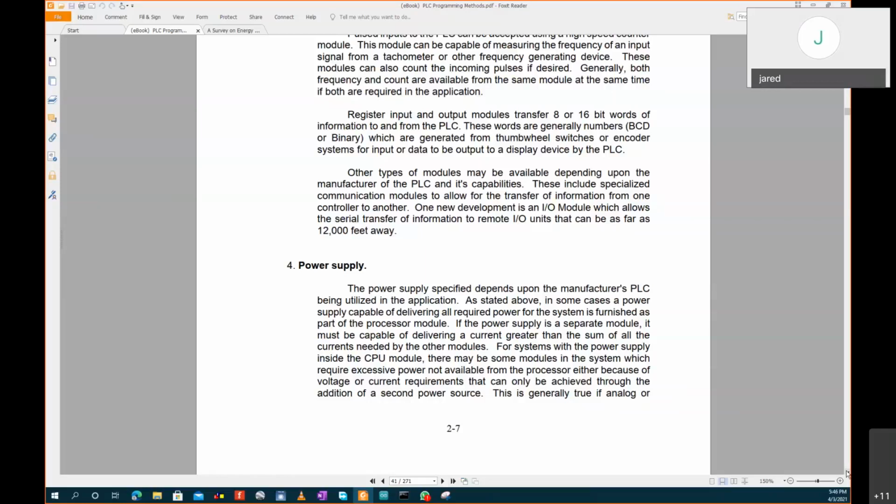And it's called hot swapping. Hot swapping is a technology where you replace a module and the PLC is still performing functions. If the module is the only one that is broken, the PLC will continue running other processes, and you hot swap. You just plug the pins and insert it. The PLC picks the addresses and continues running the other operations. You don't even realize how it happened. But that's how hot swapping is done.